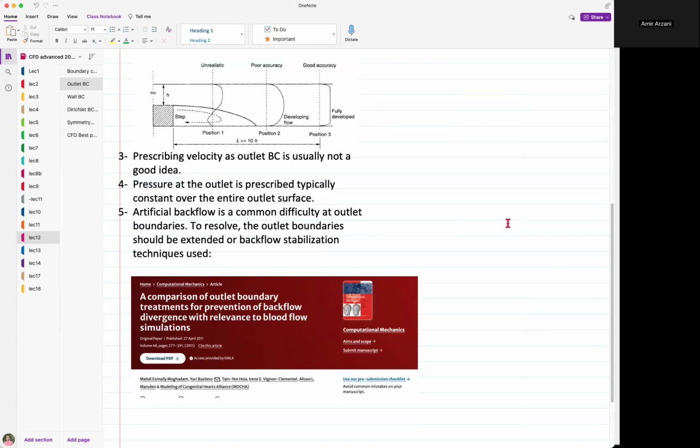To resolve the issue, the easiest way is to just extend your outlet sufficiently. The second choice, which is a better choice and more efficient, is to use backflow stabilization methods. There are different backflow stabilization methods developed for finite element simulations. I'm including a paper here. I'll include a link in the description box where you can see these methods that are used for backflow stabilization.